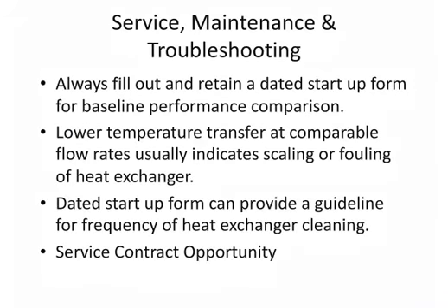Service, maintenance and troubleshooting. Always fill out and retain a dated startup form for a baseline. In other words, when you go to start up a unit, you should always be doing a commissioning worksheet. And in there is going to be your flow rate and your temperature differences, making sure that the capacity of the machine is where it needs to be.